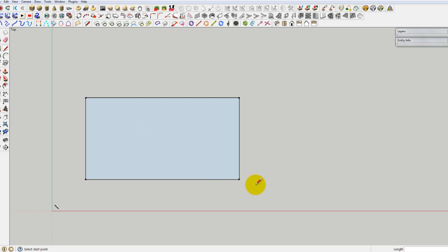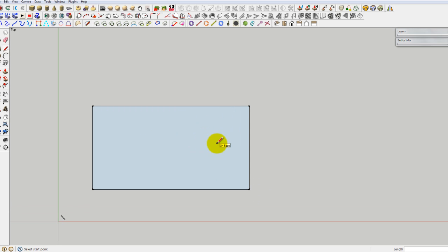And suppose you want to make a wall out of this, with some thickness of say 0.23 meters. This is basically the offset command, which is pretty similar to AutoCAD, but it doesn't work the way it works in AutoCAD, because in AutoCAD we can offset the line, whereas here we have to offset the edges of the surface. So if there is no surface, we cannot actually offset this whole thing.